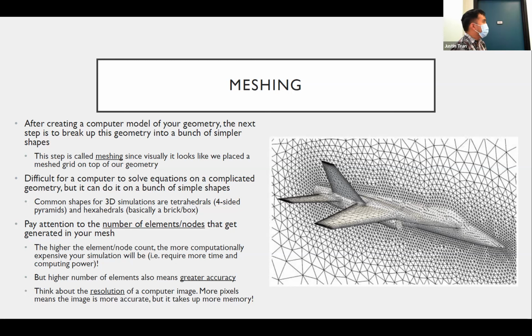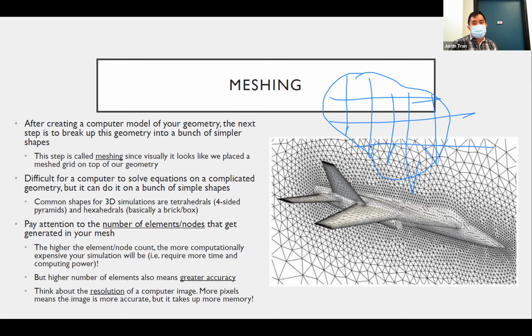Okay. And so when you mesh your geometry, and you'll see when we get to this in Vascular, you can specify the size of the elements, right? And so let's say that you have kind of a complicated geometry, like this, right? You can choose to have really big elements, right? And so let's say that we break this up into elements that might be this size, okay? Right, and so there's a specific setting for it.